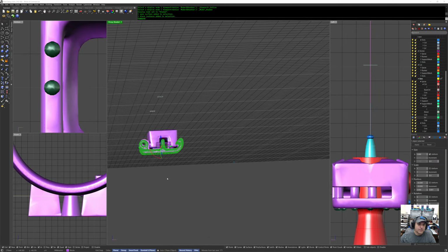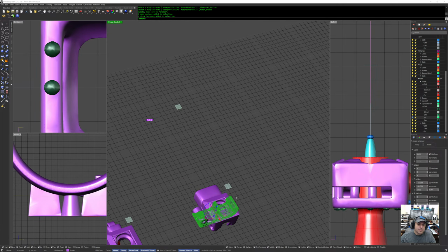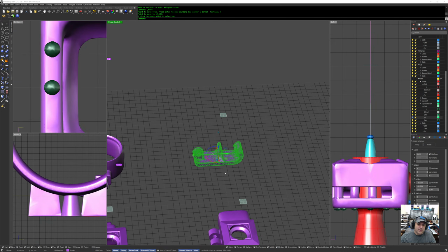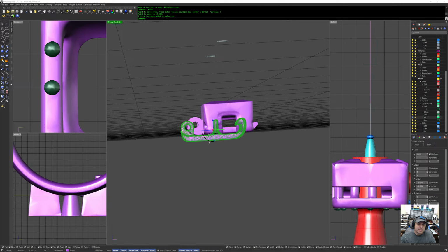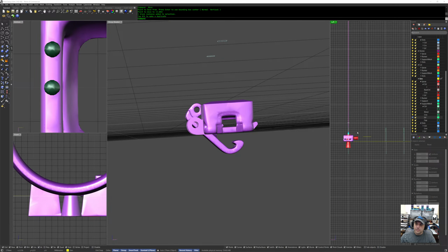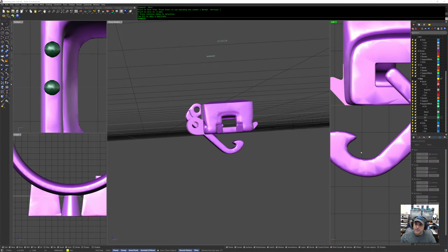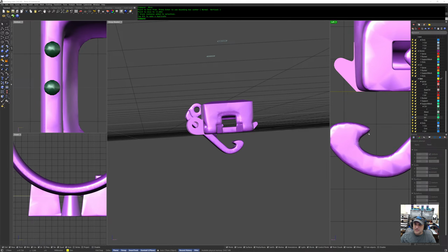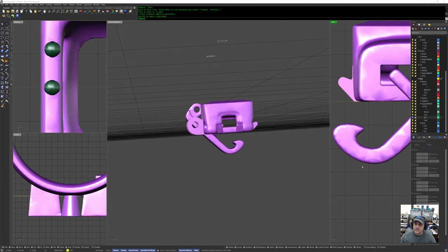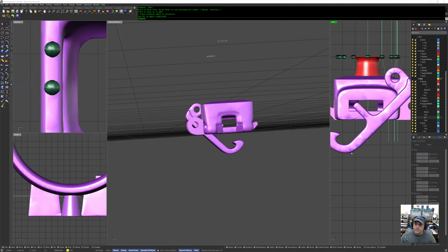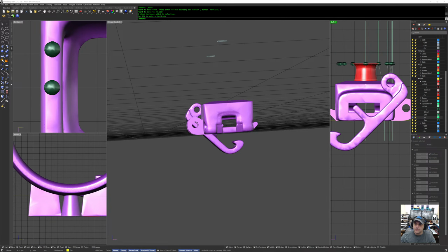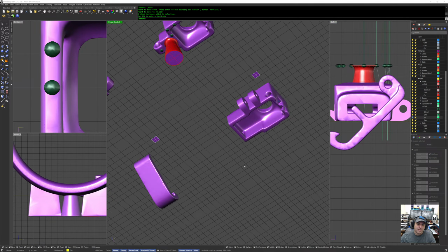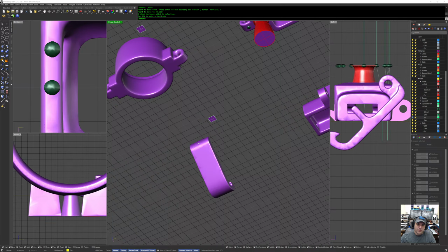I want to do that, but for this guy, and I'm going to need it one other place, which is on this guy. So let me move him from there to there. And I'm going to do that because I'm going to print this at like a 45. I think a 45 will work for this. Yeah, that's a little bit of an overhang, but it's climbing. That should be fine. I'm going to put a sprue down here, but then I want to put a line support across the back of it.